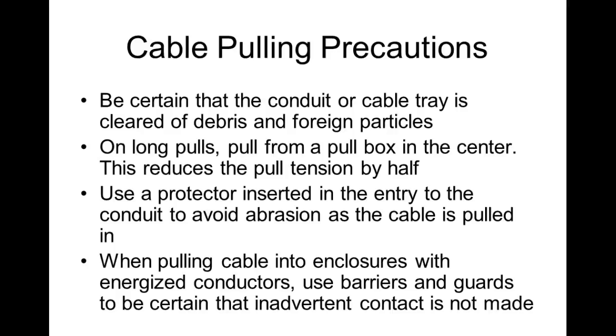We use barriers and guards to be certain that no inadvertent contact is made with those live conductors. So I got boxes, and I'm pulling a cable, and they can't shut the plant down for me to pull that new cable. So when I open that cabinet up, there might be some high voltage in there, right? You understand? And I'm trying to pull the cable. But what we need to do is put up barriers and guards and everything around those live circuits so those guys won't accidentally get in there while they're pulling those cables.